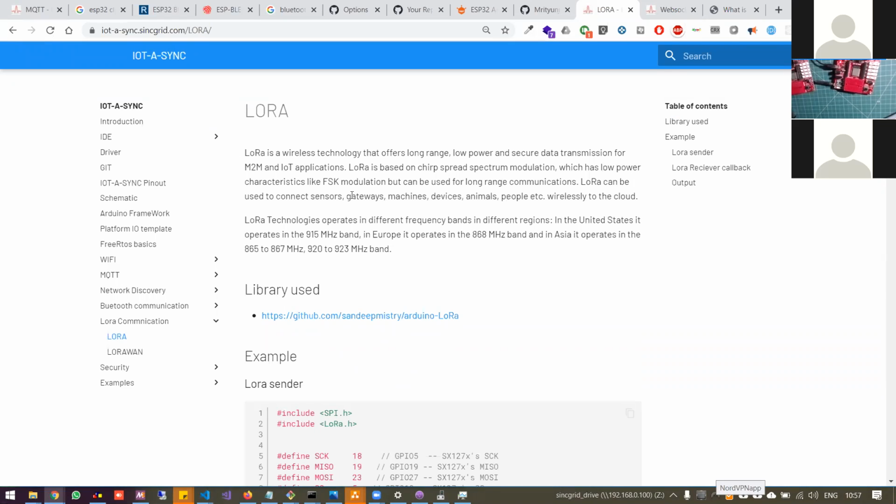on different bands. So in India, we operate from 865 to 867 megahertz specifically. There is a proposal forwarded by the TRAI in 2017 of making 868 megahertz also available in India, though it is not in use currently, especially in India for any particular industrial or medical use. So it was a proposal basically proposed by the TRAI to use this also.